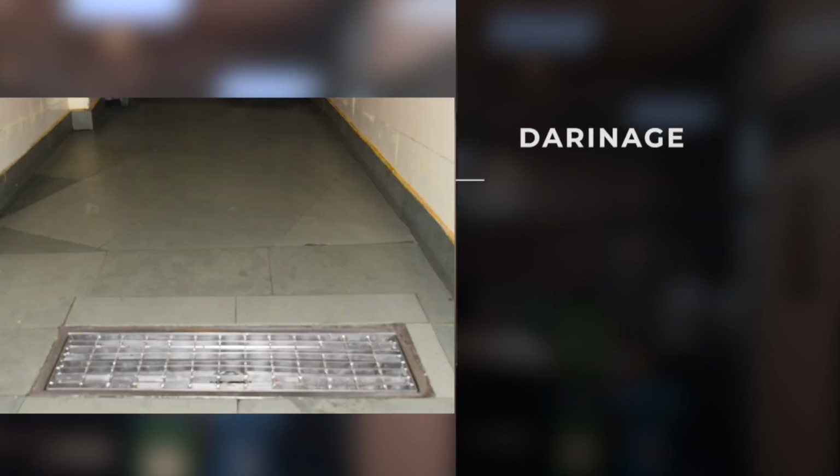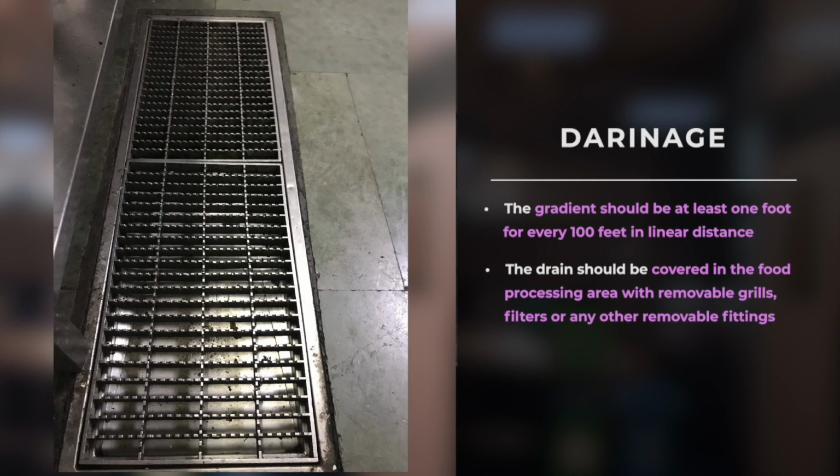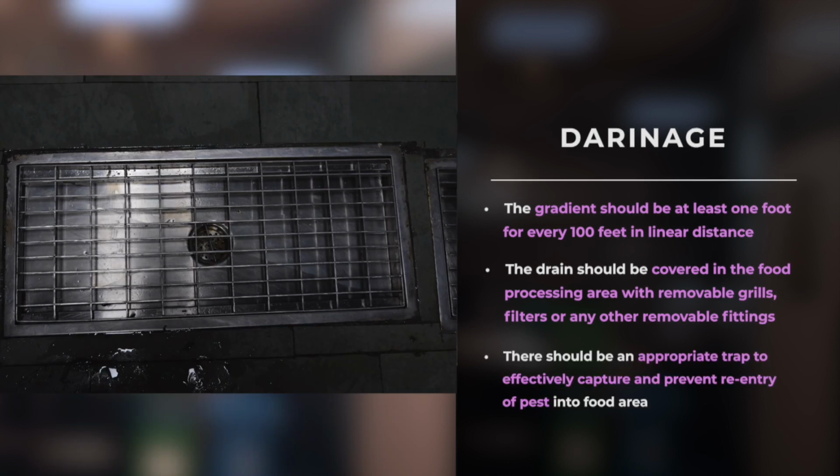The gradient should be at least 1 foot for every 100 feet in linear distance. The drain should be covered in the food processing area with removable grills, filters or any other removable fitting. There should be an appropriate trap to effectively capture and prevent re-entry of pests into the food area.